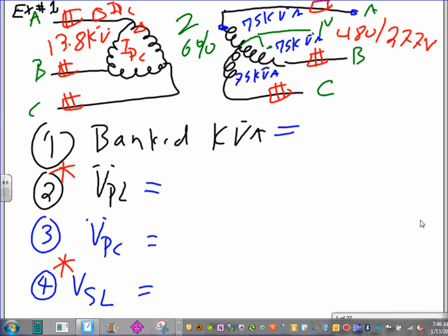Or you can have the big fat fluffy three-phase transformer built in. As if they put all these single-phase transformers, instead of one standalone device, as a coil. Coil 1, coil 2, coil 3, built into a three-phase transformer. That's the most common one. This one you're going to encounter a lot. Utilities use this a lot, as well as industrial. You could see this one in an industrial plant. Commercial building, you wouldn't see it. But what we're doing, Adam, we're doing industrial, right? So you could encounter this situation.